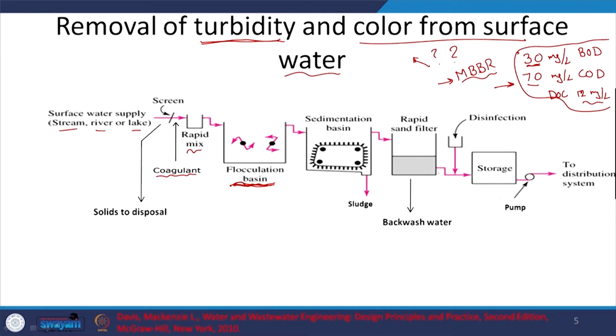So you will have a sand filter, and in the sand filter itself, you will have quite a few pathogens that can be removed, let's say, right. And obviously the last step is always disinfection. You want to kill the pathogens that are left. You are going to disinfect the water by adding a disinfecting agent, which is typically an oxidizing compound or UV, right. Why UV? It will damage the DNA or the RNA of the pathogens.